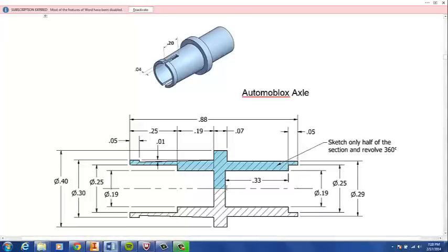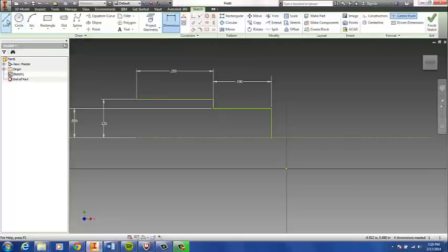Okay, so we'll come over some unspecified distance. All right, we're up. That's the 0.19 again, and we've got 0.33 across. Okay, so this is the part that is unspecified. All right, we'll come up. I can avoid dimensioning if I make sure I constrain it to the previous line that had a diameter of 0.19. And it didn't get that previous line, so let me do that.